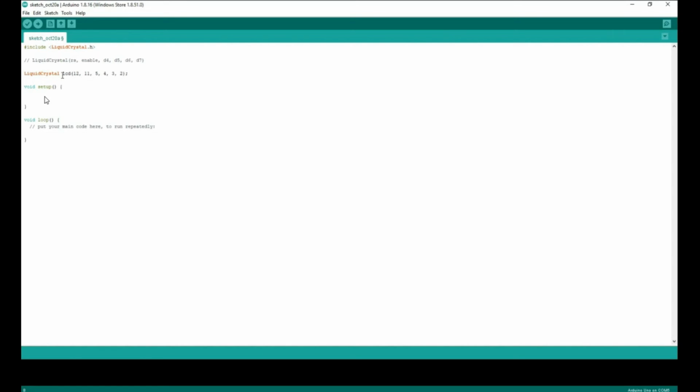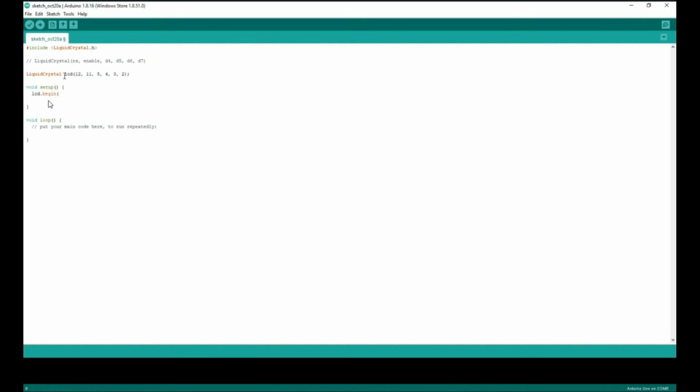Now let's go to the actual code. We now go with the display type declaration, LCD begin 16,2 and it tells us that it has a 16 character by 2 line display. Now let's print a string with LCD print. That is printed by default on the first line of the display, starting from the leftmost character, the one defined as the 00 character. With delay we make a small delay of 2000 milliseconds, therefore 2 seconds, before going to the next view.